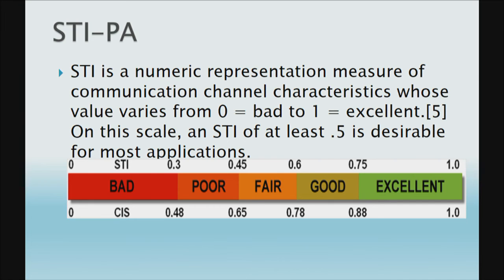Have any of you heard of STIPA? Okay, so it looks like a lot of you aren't familiar with STIPA. This stands for Speech Transmission Intelligibility for Public Address Systems. And it's actually a measurement. If you've ever heard the signal, it sounds really weird, like something going on underwater. But it's been designed to test systems for their intelligibility. This was really important in public address systems like at an airport or a shopping mall, where they have to have clear, concise directions. You know, everybody go to this corner over here. But the folks putting in public address systems in our world have started adopting it as a good overall measurement. And you might require or ask that a STIPA reading be done. As you can see up here, they mention 0.6 or 0.75 as being a good reference for that. If you're down below 0.3, you've got some issues going on there.